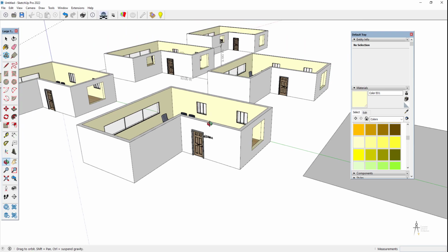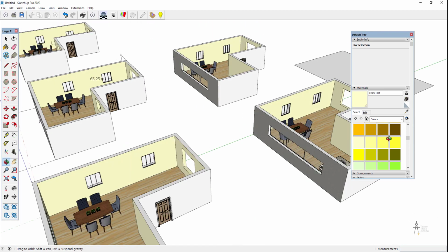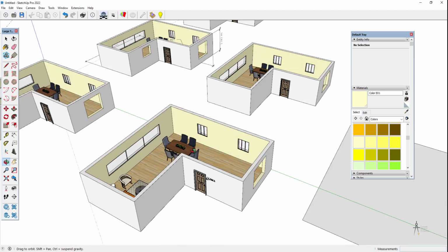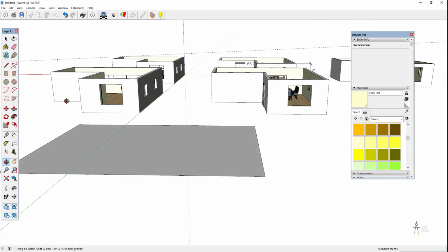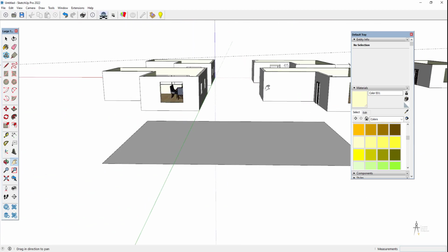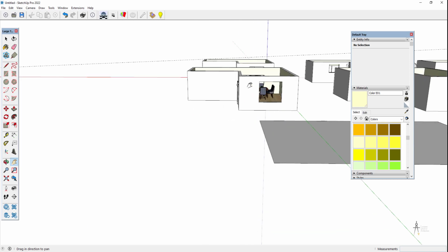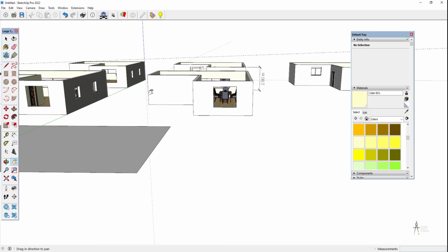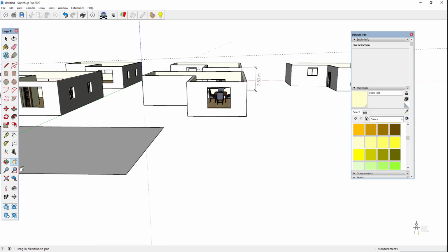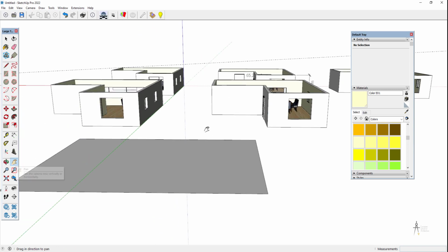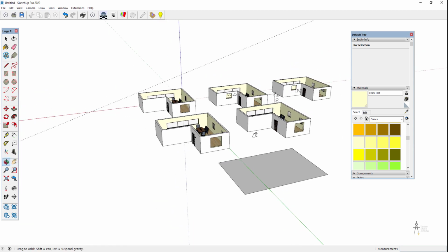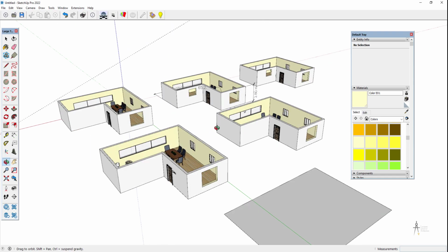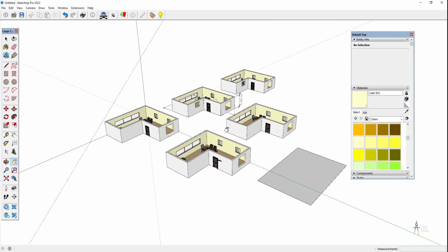Okay, you can edit it and do whatever you like with it. Check out the difference between orbiting. Okay, I'm clicking on the center button of the mouse, and panning. Panning, sort of you move sideways. Okay, it's a very important tool. The rest are also very useful, but the pan tool we're going to be using a lot.